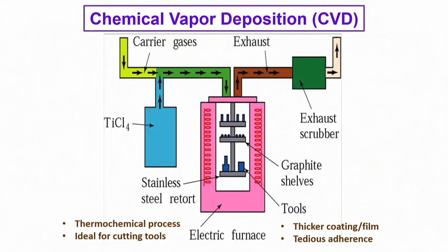Now, compared to PVD and sputtering, we are going to discuss chemical vapor deposition, CVD, which is essentially about the same thing. We are thinking about low thickness deposits, films, typically a few tens of micrometers or less. In the limit, we can create very thin layers, a few tens of nanometers, in alternate sequence.